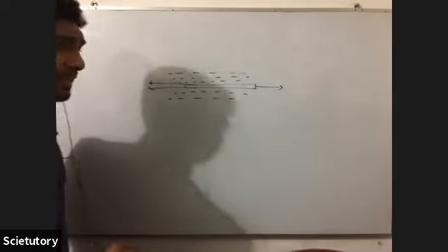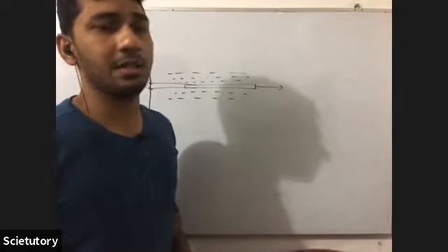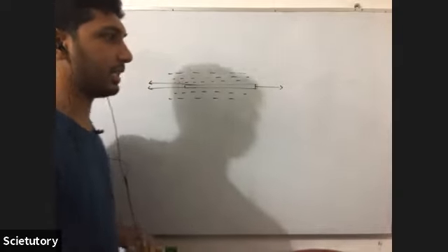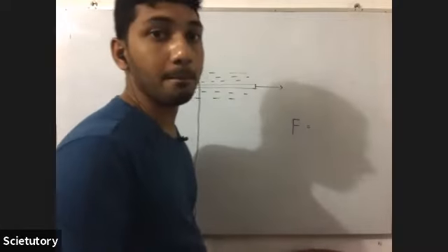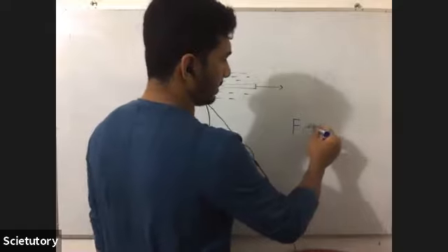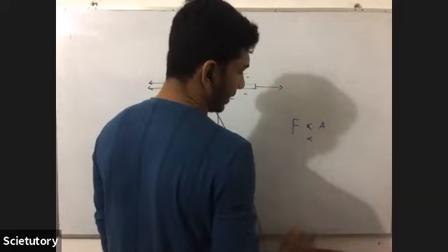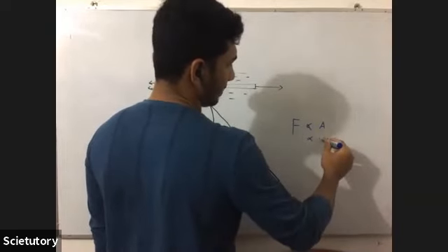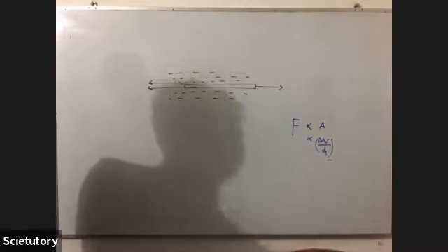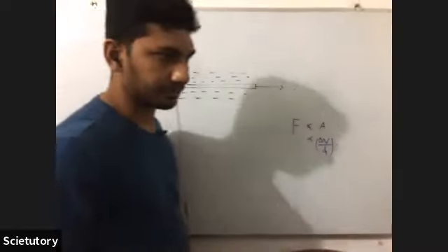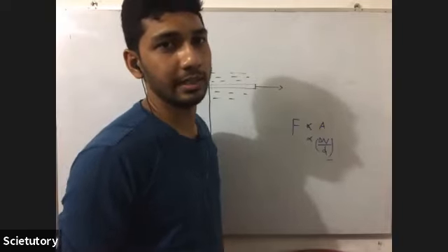So this is similar to the friction that you see in solids, but it has a different kind of equation. So what's that equation? The viscous force is directly proportional to the surface area. And it's directly proportional to what? Delta V over D, the velocity gradient.